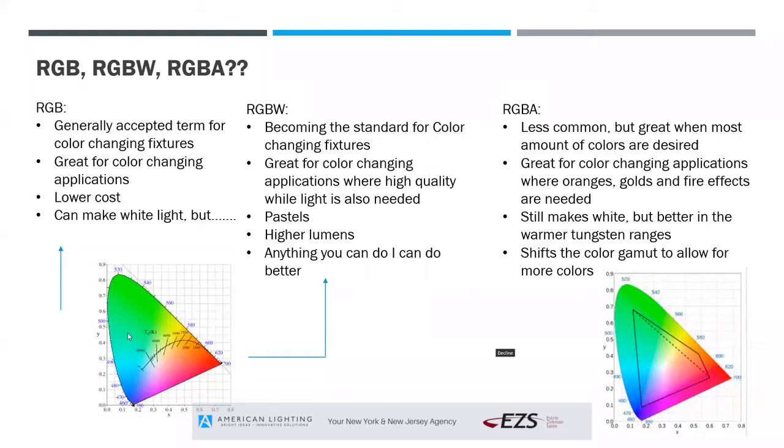That's what we talked about, those 16 million color combinations. You'll also notice this black line here in the middle. It's a little hard to see, but that's called the black body curve, and that's actually where all the white points sit. So you can start down at 1900 or whatever that says and go all the way to 10,000 CCT. You can do white points with RGB because within the gamut, you have your white points.